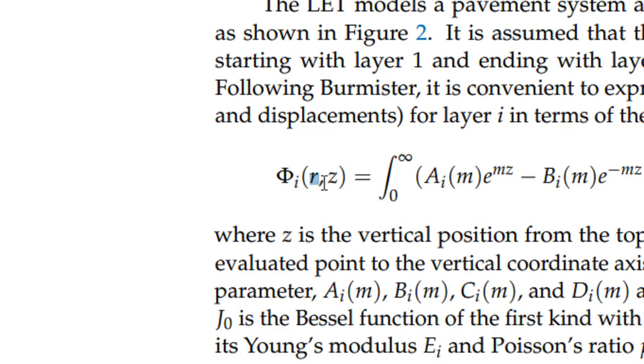The sixth point I'm trying to bring your attention to is the comparison of the FEA results with analytical solutions, like Boussinesq or Burmister layer theory. For example, the Burmister solution for stress in a layered system can be used to check the ABAQUS model accuracy.